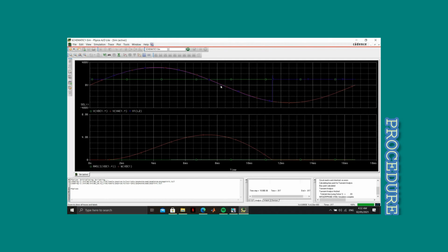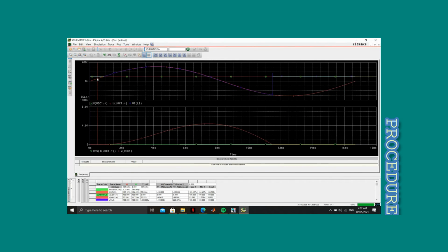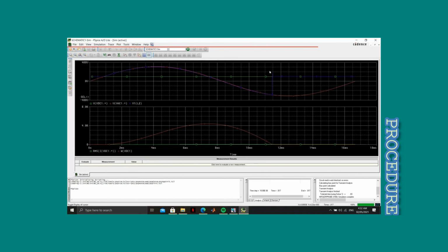On the other hand, upon reaching a certain voltage, in this case negative 287.561 volts, the diode turns off, which means it would stop conducting. If it stops conducting, the only voltage source would be our DC voltage source. That's why the voltage waveform becomes a steady 100 volts.